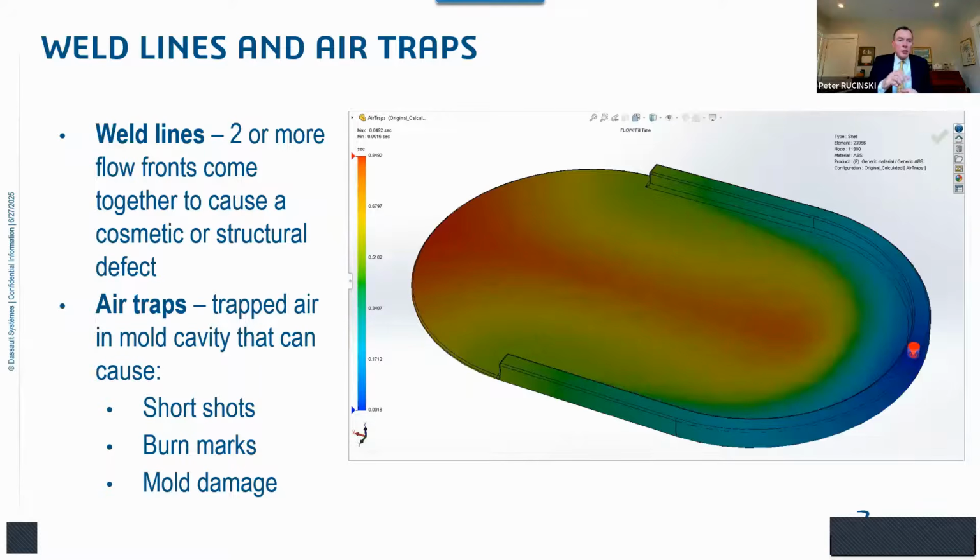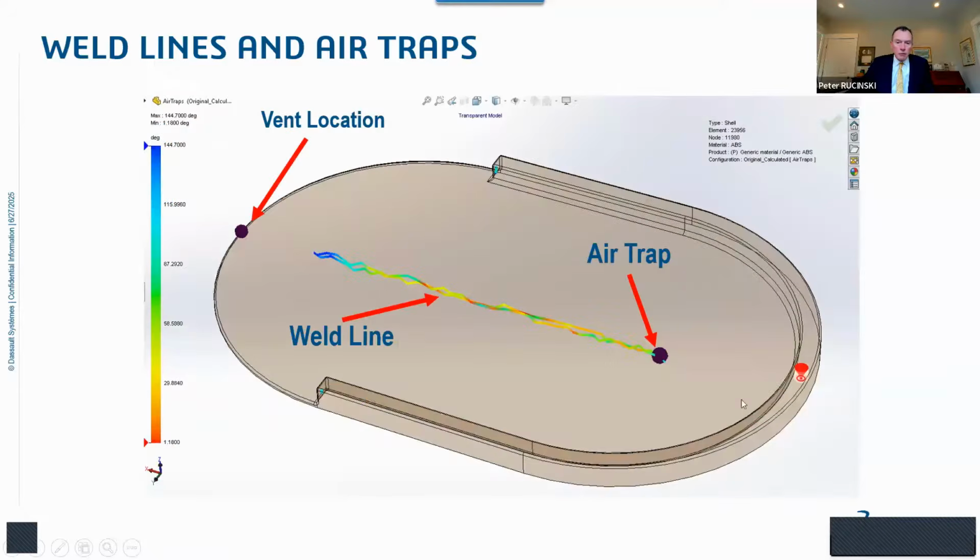If it gets to the point where you get the small explosion, that will cause a burn mark on your part. It more than likely will cause an unintended through hole, and that little explosion is usually going to damage your steel core and cavity surfaces. So that's one you really want to avoid.